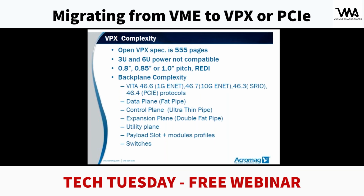When you go to a backplane complexity, you have all these different fabrics, protocols that you can run on the backplanes. So here's a few examples. The one that's typically used in a lot of applications is the Vita 46.4, which is the PCI Express protocol. But as you can see, you have a gigabit Ethernet, you have 10 gig Ethernet, you have serial rapid I/O. So there are a variety of different backplane protocols that you can run.